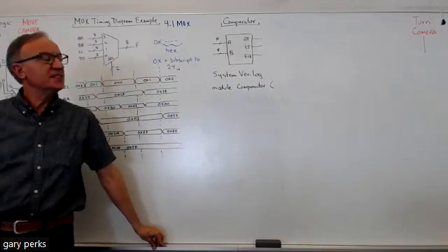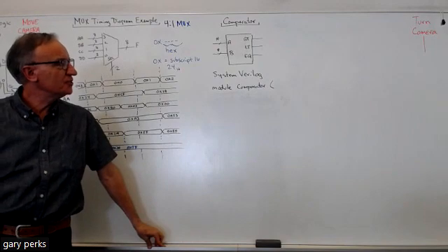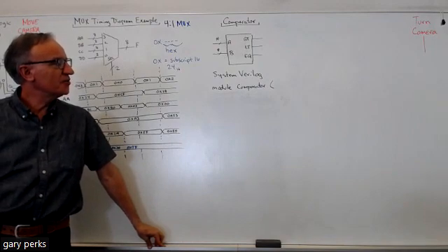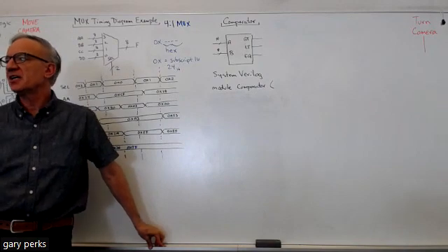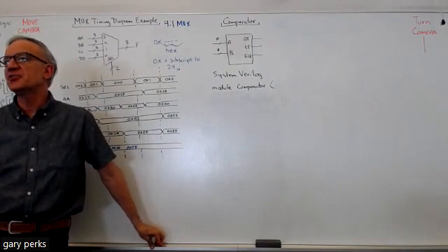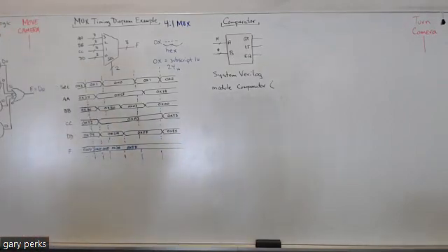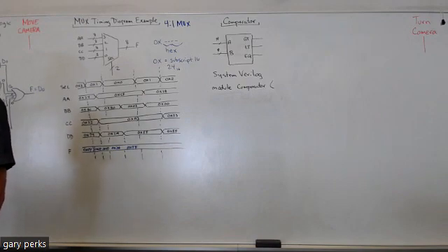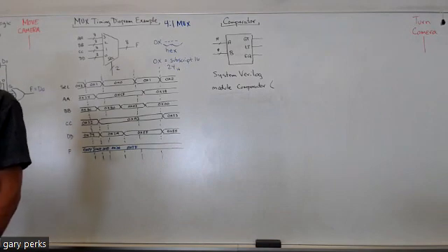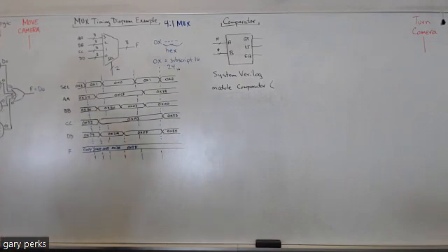All right, the next thing is I want to show you the SystemVerilog code, or an example of the Verilog code, that you're going to need in order to model the MUX. Because up until this point, what we've been doing is using Boolean expressions to model hardware, right? Lab 0, Lab 1, the lockbox, and also when you did the half adder and the full adder for the RCA, you were using Boolean expressions along with an assign.